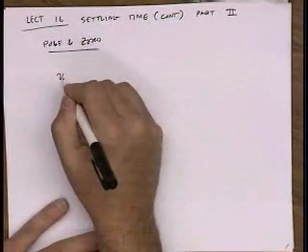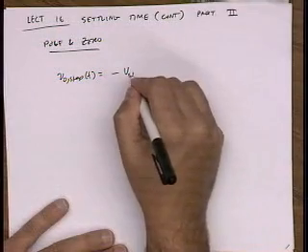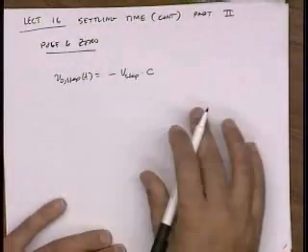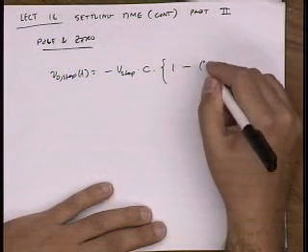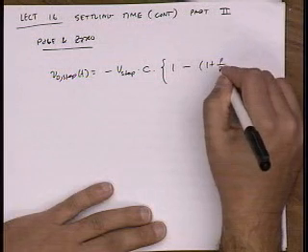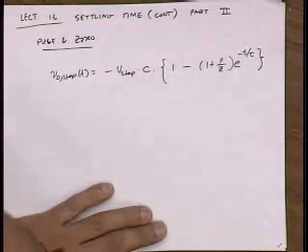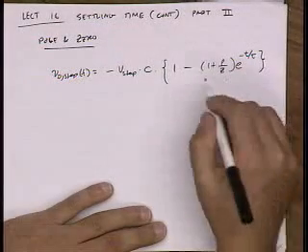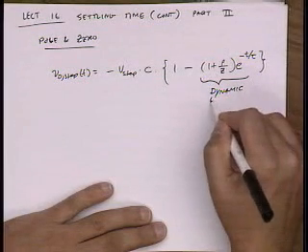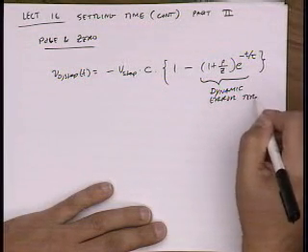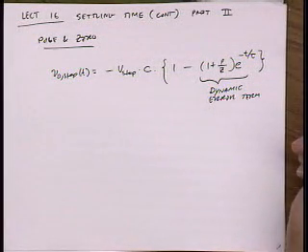And we found that the output step response is basically the input multiplied by the ideal gain that we're calling C here, times a factor which disappears over time exponentially, but nevertheless you have to wait for it to disappear, and depending on what resolution you want, you have to wait longer and longer. So this is kind of an error term. This is a dynamic error term.